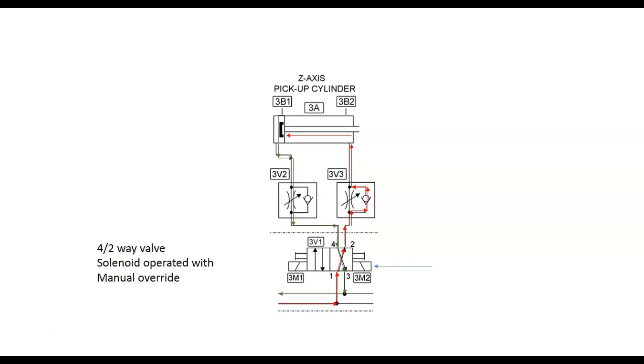So you can see pressure comes in off our manifold. Both lines run manifolds except for one of our actuators, and then the cylinders, the valves mount on the manifold. Now, what's neat about the Festo is the manifold actually is on the side, and all your piping is done through the actual valves themselves.